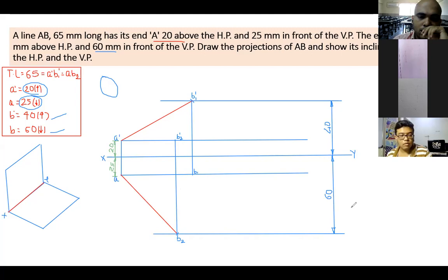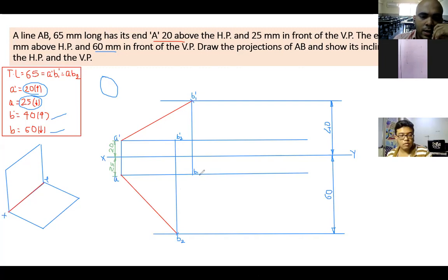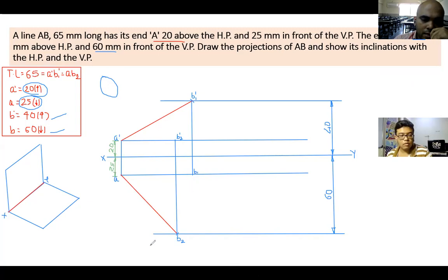So this is what you have done till here. Now what you have to do next is take the distance A B1 in your rounder. Everyone just listen: A B1 distance, with A as the center, and then make an arc till this line.